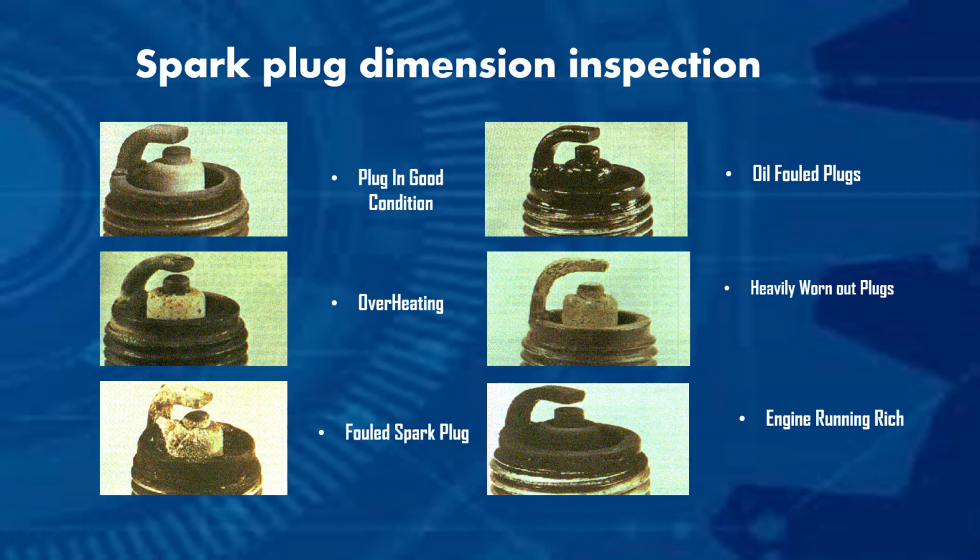This coating is conductive and will cause a misfire. This may be observed as fuel and can be dried off. If this is the case, you have an ignition fault and the plug is not firing. Heavily worn out plugs. Worn-out plugs start to operate less efficiently and thus start to coat with a conductive fuel and engine byproduct, and plug efficiency is diminished and the extra gap places a necessary load on the ignition system.